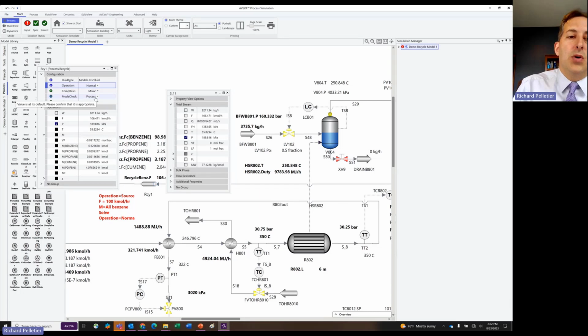All right. And so this is what you're trying to get to in terms of the equation-oriented solving approach, right? This is going to make it the most robust and behave most accurately, right? But both tear and normal at this point are basically the same solution. It's just tear is going to have more calculations occurring in the background, so it's a little bit more involved in order for it to solve, right? But you start by manually working it towards that solution.